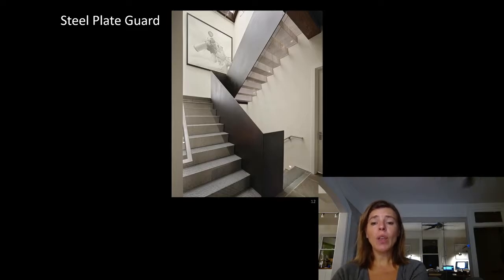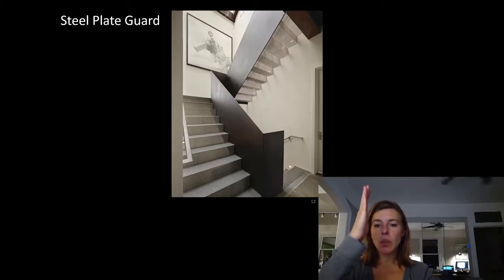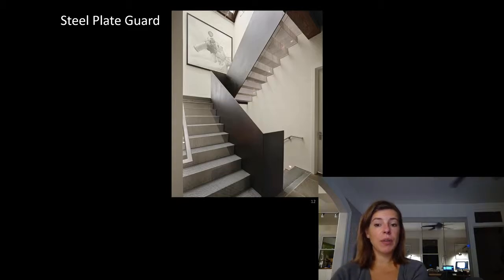and then hear all the information come out through the lecture. We need a guard when we're adjacent to something more than 2 feet off the ground. So if we have more than 2 feet off the ground, we structurally need a guard. So you're doing landscape work and you've got a curb that is 1.6 meters down into something below, no guard needed.